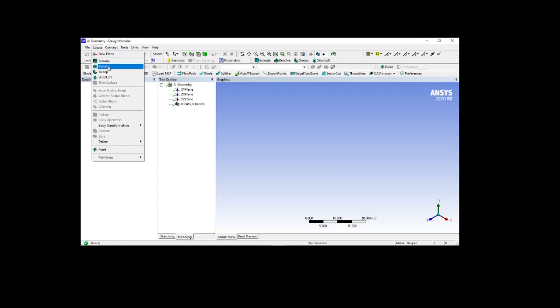Before going to all this, I will come from the bottom, because at the bottom you may watch the attractive feature of our design modeler. That is, it will create ready-made shapes for us that we are able to access. The first one, I will come from the bottom, is the primitive. In the primitive, you will see a lot of options here. One is the sphere, box, parallelepiped, and cylinder, cone, prism, like that.